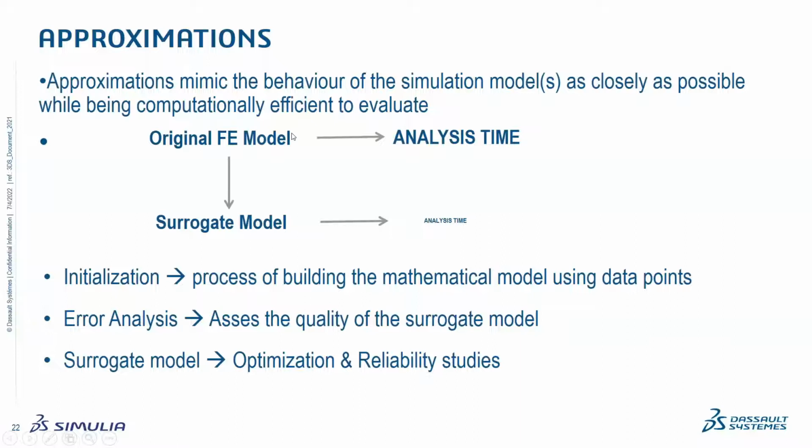So for that we try to create something called approximation models, which mimic the behavior of the actual simulation model and create a relation between your input and output. That way your overall runtime is reduced drastically. If you have some 10 parameters, accordingly we might want some 30 or 40 iterations only, not some 100 or 1,000 iterations that the optimization wants. So we can run those 20 or 30 design iterations DOE and create a relation between your input and output. That way it can save a lot of time. At the same time, you're reducing your computational space as well.